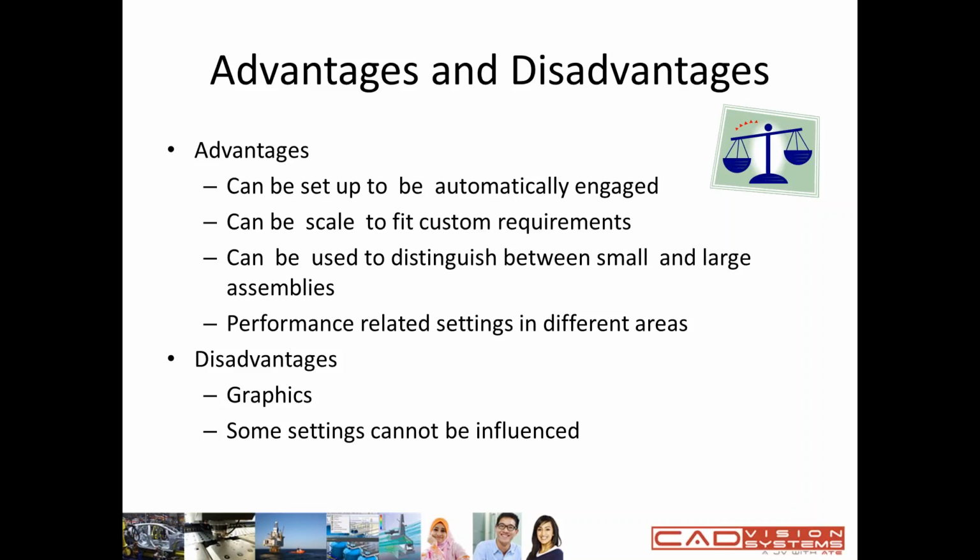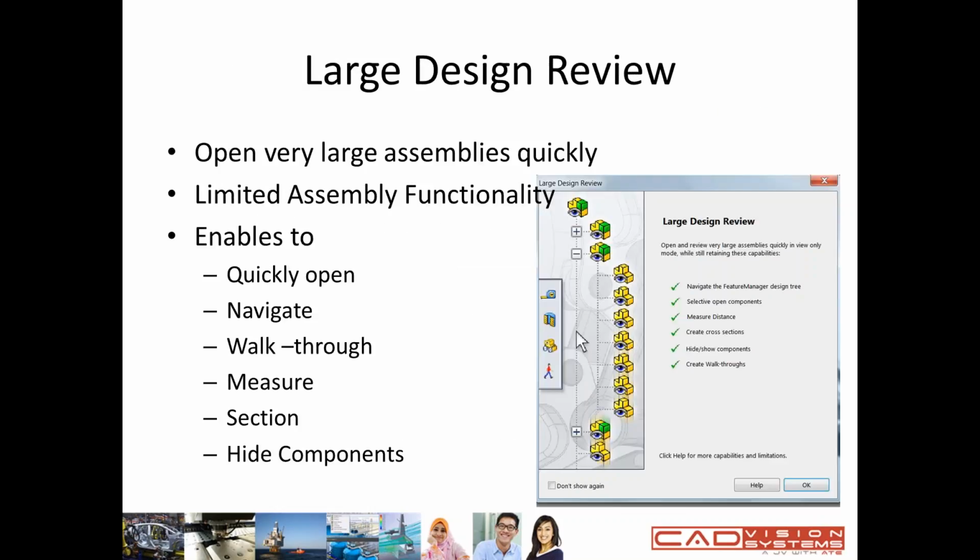So when can you use large assembly mode? Whenever you are dealing with a very large assembly, you can just turn on large assembly mode, or the system will automatically turn it on. Basically, you will speed up your system interaction. It's also a one-click solution for different performance-related areas. So it gives different behavior for small and large assemblies. Okay, so go to the next one.